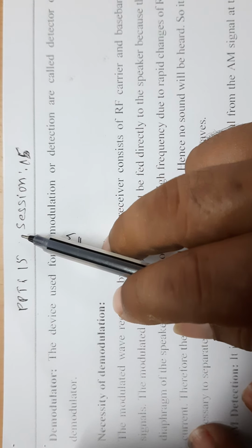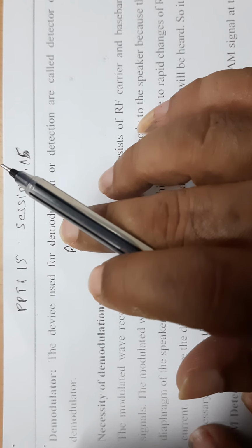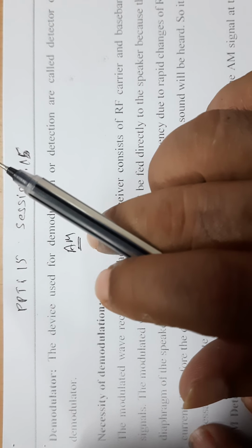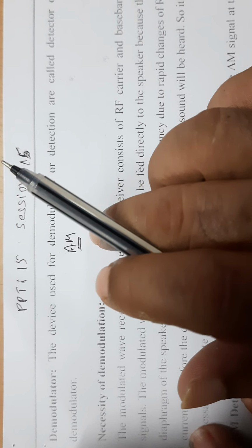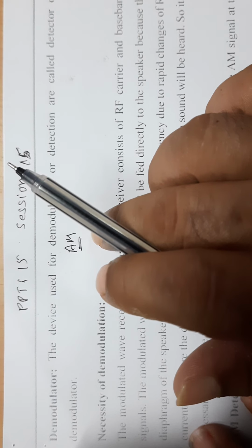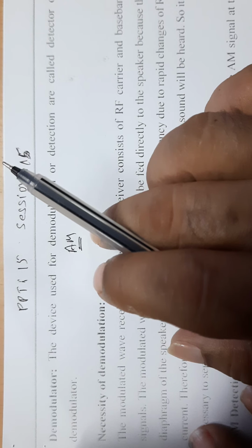Demodulation is the process of separating the high carrier frequency, called radio frequency, from the low message signal frequency. This high carrier frequency is removed to the ground and the low message signal is then fed to the loudspeaker to produce an original replica of the sound. This is demodulation. Modulation always occurs at the transmitting station, whereas demodulation is the reverse process of modulation. Here we are separating the high carrier frequency from the low message frequency. It is always obtained at the receiving station.